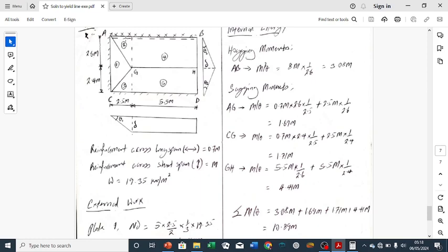The length of the yield line here, what is the length of the yield line? This place should be 2.6. Let me have a look at it. Okay, for the yield line we are calculating, this vertical yield line, the length is 2.6, while for our theta, the distance from the axis it rotates about is actually 2.5, so that is why our theta is 1 over 2.5.